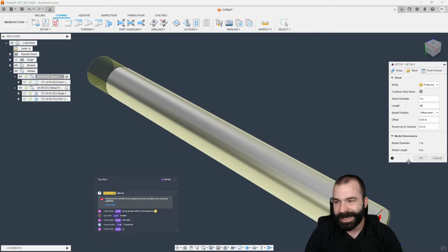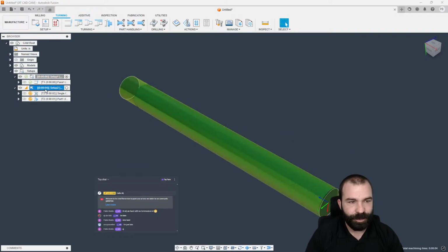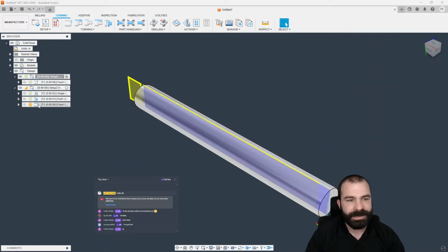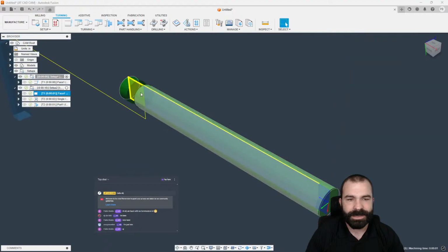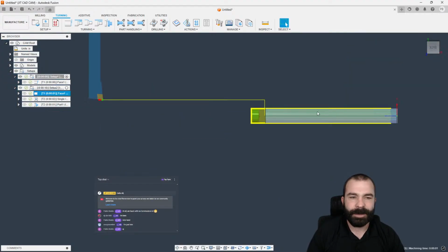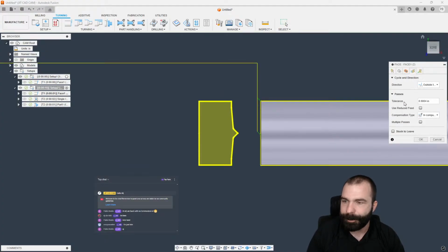Let's say it was 10 inches, right? Some of us are pretty legendary for this move here, but I'm going to take my facing, a little copy and paste Hollywood magic, reorder it. We're going to generate it once again. As you guys are seeing, that sub-spindle situation, we would have to turn on multiple step overs.